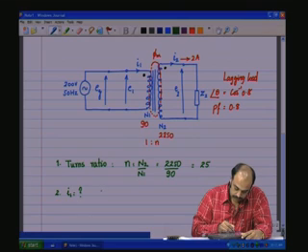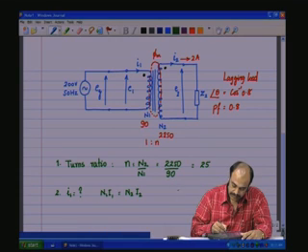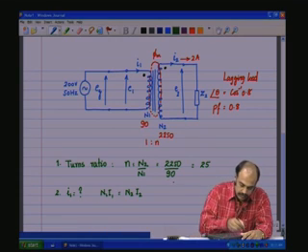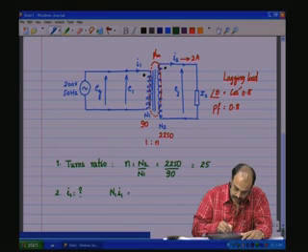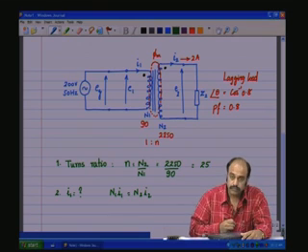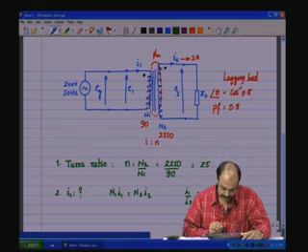So, we know that N1 I1 ampere-turns should be equal to N2 I2 ampere-turns, and also from the power equation we have earlier seen that, let me use the same notations. N1 I1 is equal to N2 I2, because we see that I1 by I2 is equal to N2 by N1, this inverse proportionality for the currents.